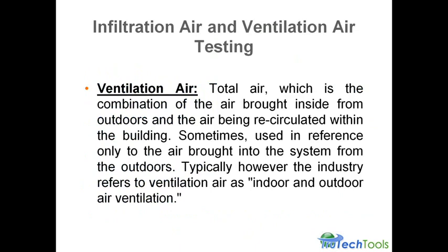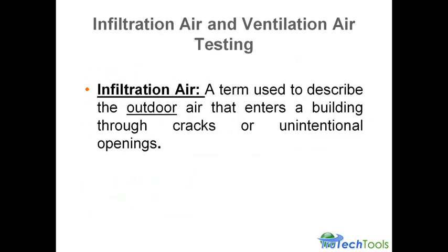Ventilation air is the total air, which is a combination of air brought in from outdoors and air being recirculated within the building. Sometimes it's used in reference to only the air brought into the system from the outdoors. Typically, however, the industry refers to ventilation air as indoor and outdoor ventilation. If you're talking about an atmospheric draft hot water tank, the ventilation air is the total air in the house that's available. For a sealed combustion appliance, it's the air outdoors used for that same process.